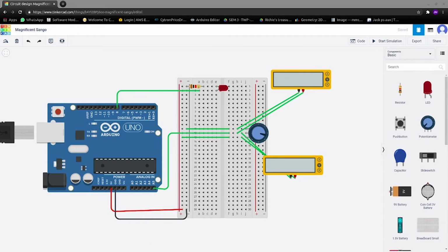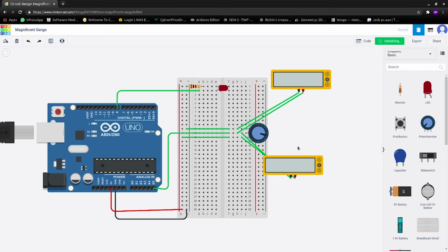The potentiometer is actually a really simple device. All that the potentiometer does is it quote-unquote cuts the voltage into two parts. We can demonstrate this here using two multimeters, one connected from the ground over to the output, and one connected from the 5 volt over to the output.